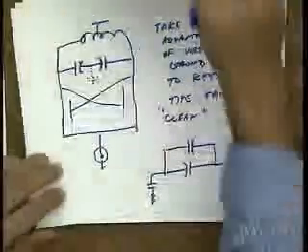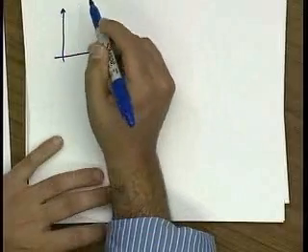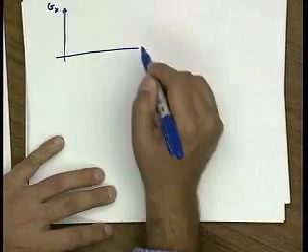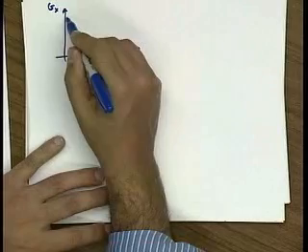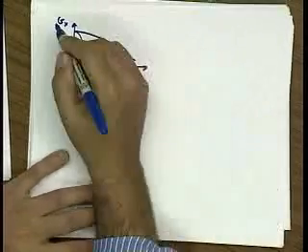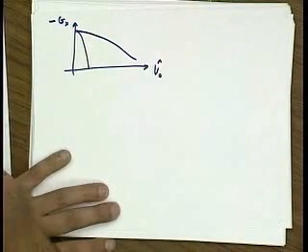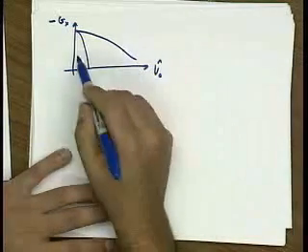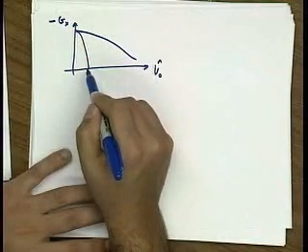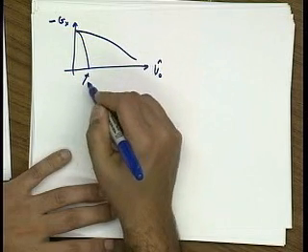Actually, that's probably worth writing down. So in fact, I think it was David who pointed this out a few lectures back. So if we compare the nonlinearity, the negative resistance of a MOS versus a BJT differential pair, it might be something like this. So this is the minus conductance of the device versus the oscillation amplitude. And so you can see that this device compresses very quickly and would result in a very small output amplitude.